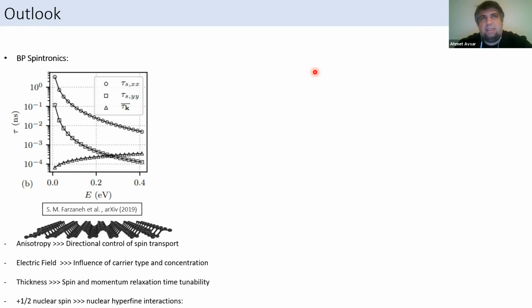The second thing is that with these conventional magnets, the conductivities are still too different, and you have this conductivity mismatch problem. But by using these 2D magnets, some of them could have comparable conductivities with your non-magnetic channel. So there is even some possibility that you might not need a tunnel barrier for spin injection. So I think there are many nice opportunities, and I'm sure many people are working on it. I see.